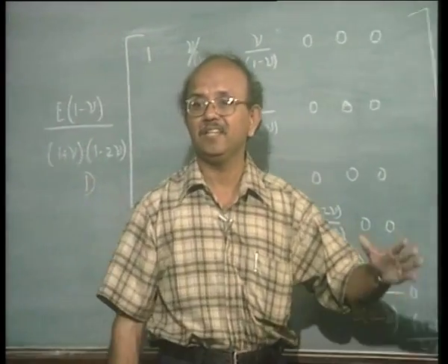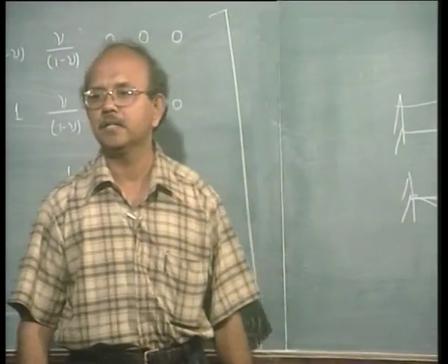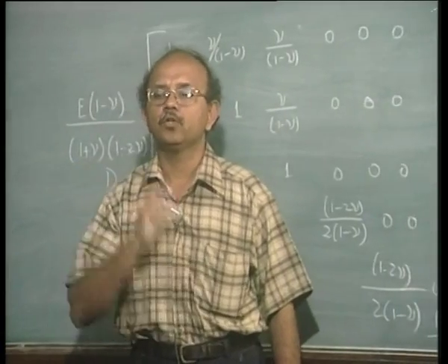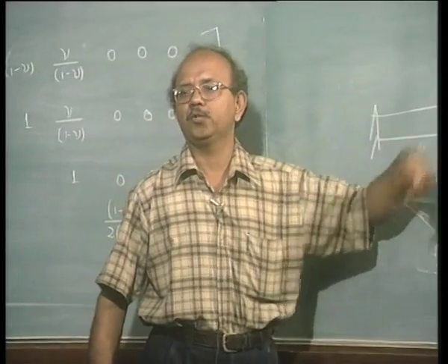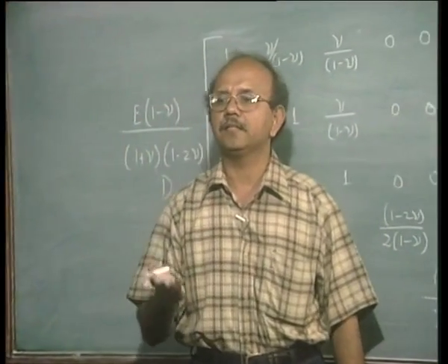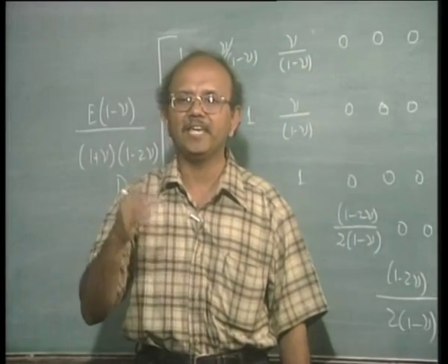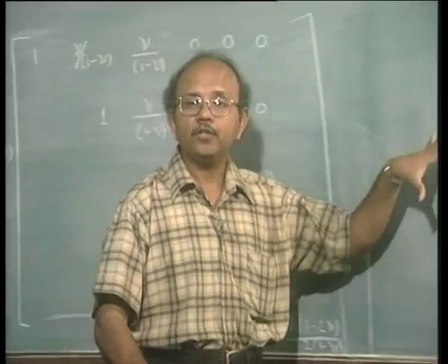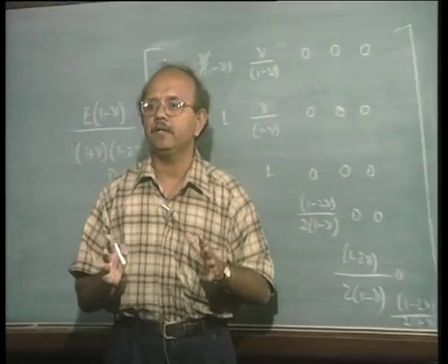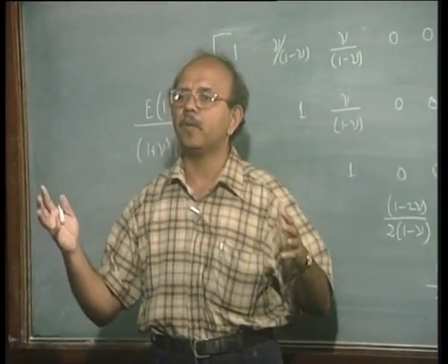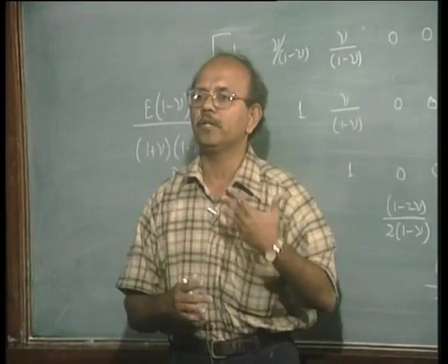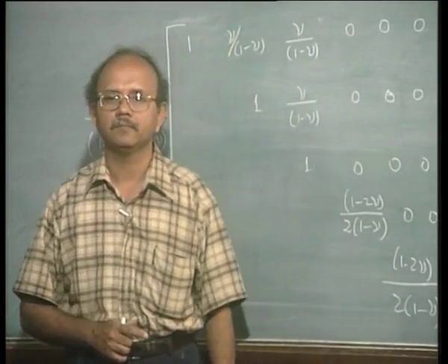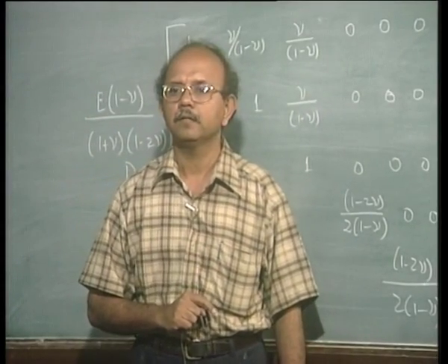So in the bar case, you had AE by L as a term to indicate the stiffness. For a torsion case for the same beam, what will you have instead of AE by L? Fantastic, that is GJ by L. So instead of AE by L, you will have GJ by L. Now you have got the point as to what stiffness is, right? So if I introduce all these things, first I started with the 2D bending, then 3-dimensional, then introduce torsion, introduce bar effect, so how many degrees of freedom will I get per node? 6 degrees of freedom. So this beam has 6 degrees of freedom. Is that clear?